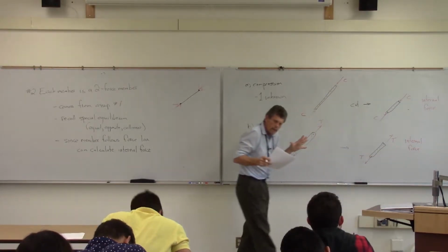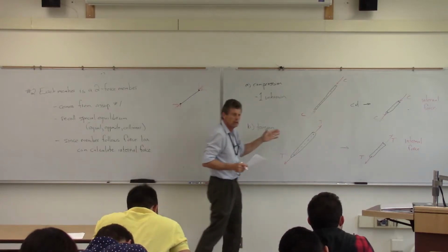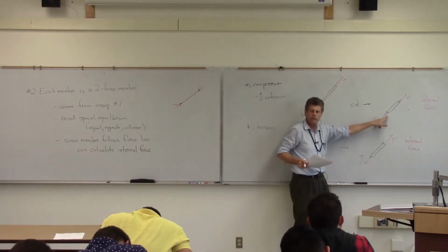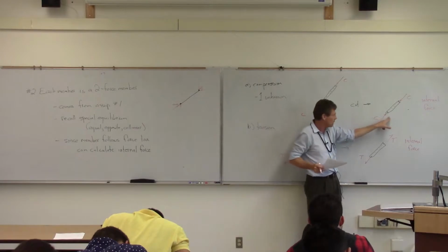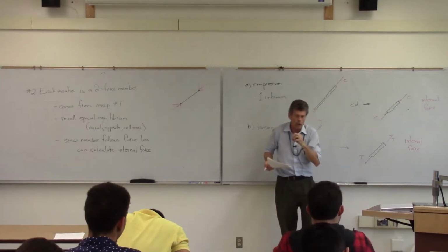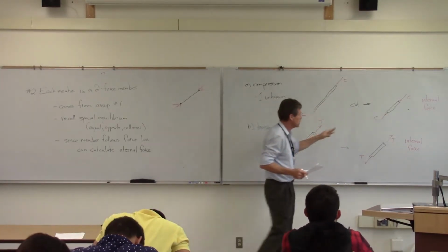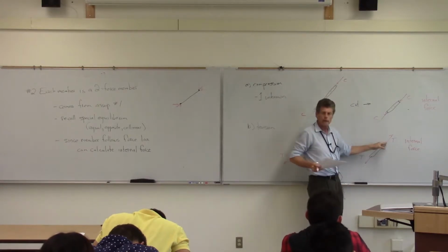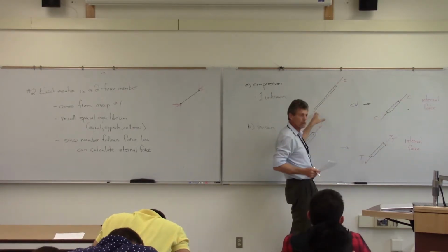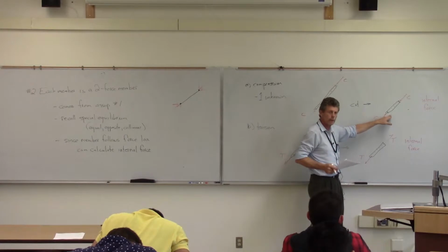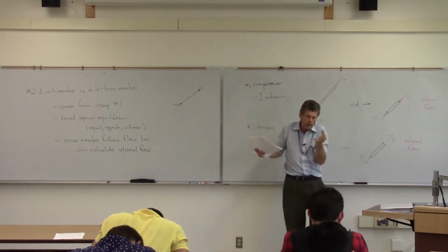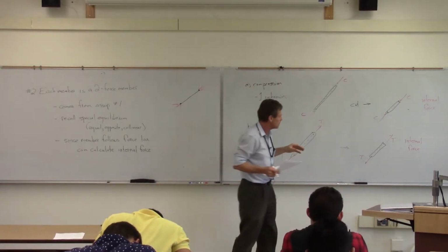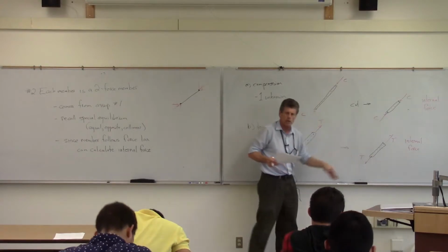And note then, what we're saying here is in terms of the internal force, it's the same as the external force. So if I can calculate the external force here at this point, at that pin, then I've calculated the internal force. So if I've calculated this as compression, it's going this way, squishing the element, then basically I've calculated my internal force of that member in compression. Same thing with tension.